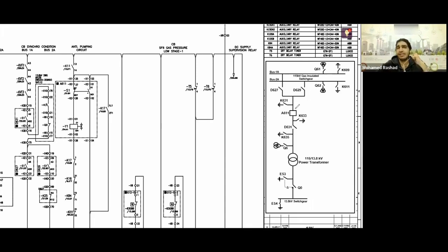We agreed that in the switchgear, the breaker can be pulled out. And I said here that I can't pull the breaker out, it's all inside. The size of the breaker is large, meaning you can't handle it as an individual. All right, remember when I told you that this is named based on its ability to connect or disconnect on the bus bar so that it can choose to look into it and operate. At the same time, what else does it need to do? It needs to perform isolation.